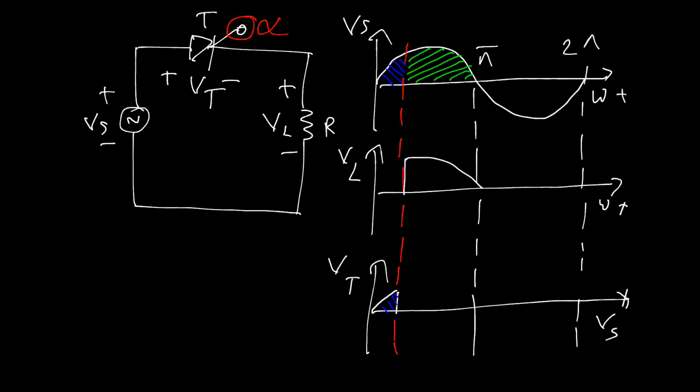So this is all about the forward biasing case, or the first half cycle, 0 to pi. In this case, we can change the firing angle by using an appropriate firing circuit. That is why resistive, capacitive, and similar firing circuits can be applied to fire the SCR. Suppose we change the firing angle. In this particular case, the firing angle was alpha. Suppose we increase the firing angle from alpha 2 to an increased value alpha 1. Then the thyristor can be fired at this point, right?